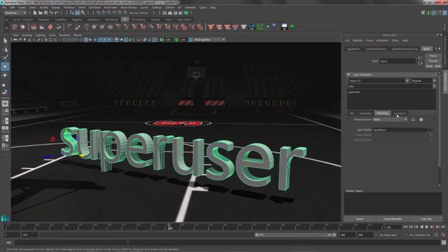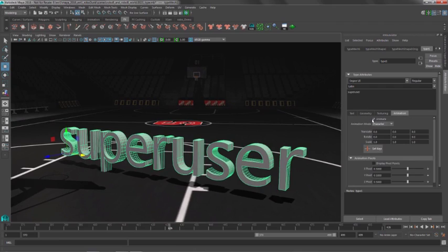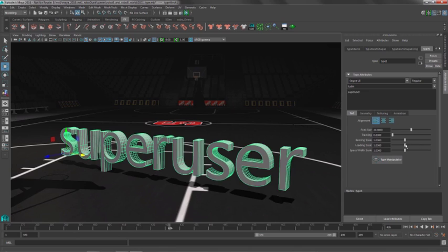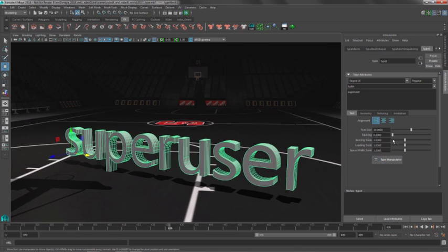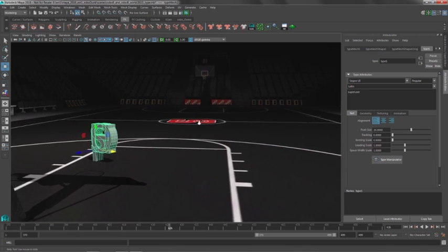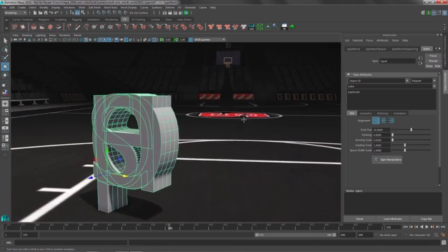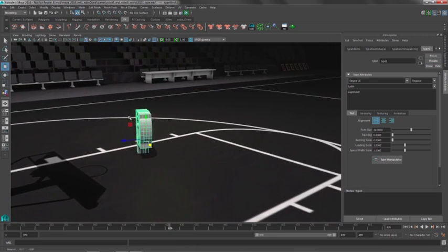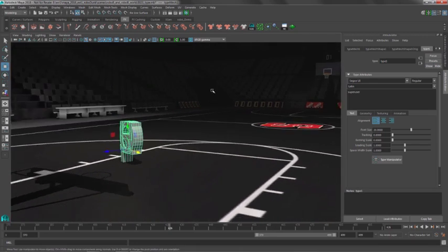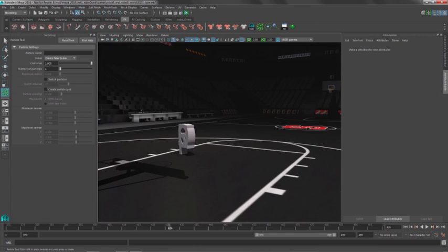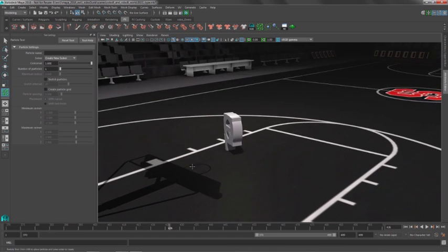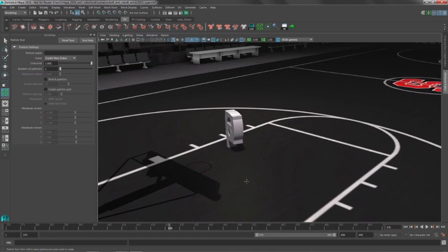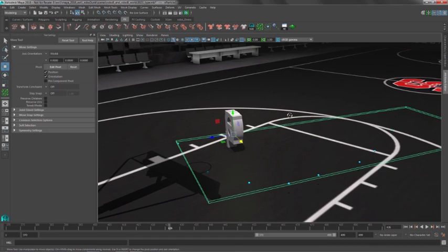And what we're going to do is we're going to animate this, but instead of setting keyframes on the animation system, we're going to have an external source drive that. So we want to zero out the pivot, or all the objects down to the origin. So if we just drop that kerning scale down to 0, everybody's basically sitting at the origin. And what I'm going to do is I'm going to end up driving these with an n-particle system. So let's go ahead and grab our sketch particle tool, and I'll just start dropping down a few particle points. So we've got our particle system inside of our scene.